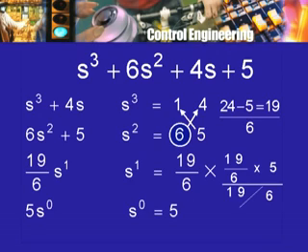From the even polynomial corresponding to this row and the odd polynomial corresponding to this row, I have obtained an even polynomial corresponding to this row. And now I have reached the end of the table because the power is s to the 0, constant. There is nothing less than that. The lowest degree in a polynomial is the 0th degree term or the constant term. So, my table ends here. It is as simple as this. Of course, the degree of the polynomial was 3, therefore, the work was not really very much involved. But what if the degree is higher? Then I will have to carry out my calculations for a larger number of steps.